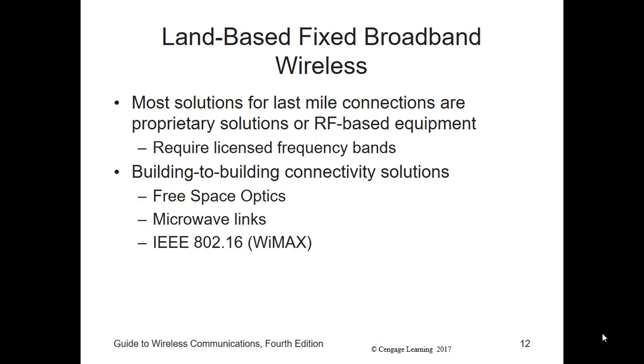Up until 2001, RF-based fixed broadband systems operated at frequencies with modulation techniques that limited implementation to line of sight only. In addition, most fixed broadband systems could only send one site to another. In other words, they're set up point to point.